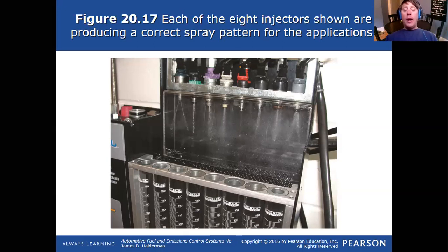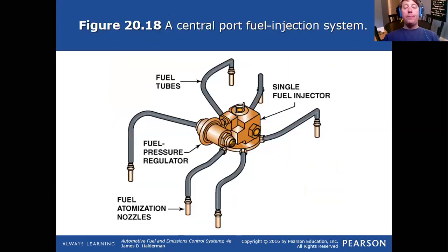Okay, and so one of the things that you can do is run a fuel injection cleaning service on a car. You can leave the injectors on the rail and run a product like Seafoam through the tank, for example. That's an injector cleaner. What that'll do is go through the injector and bust up a lot of that carbon and help restore the flow. In some cases, you'll have to remove the injectors and send them off. You can have an injector that is mechanically working, but not able to spray fuel correctly, which would cause a misfire or poor fuel economy.